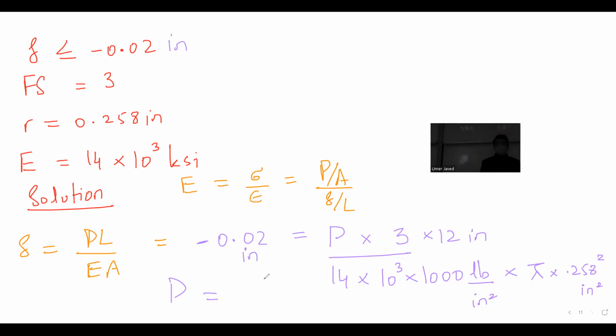Yes. In the equation, you should actually divide the P into the area, not multiply. This one, PL over EA. Okay, yeah, like this. Anyone who did that, please check. P minus 0.? No, isn't it minus?